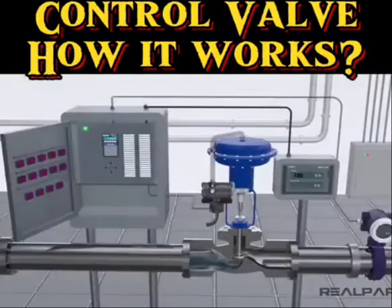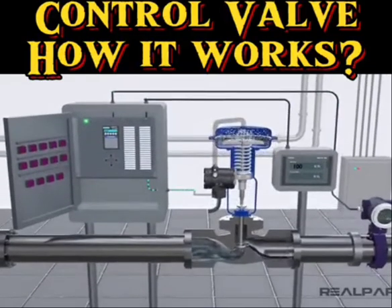The control valve receives a signal from a controller, such as a PLC or a DCS, in order to operate. The controller compares the actual flow rate to the desired flow value, called the set point. The controller will produce an output to move the valve to bring the flow rate to the set point value. Because of how pneumatic actuators are built, a control valve will fail to a specific position when a loss of